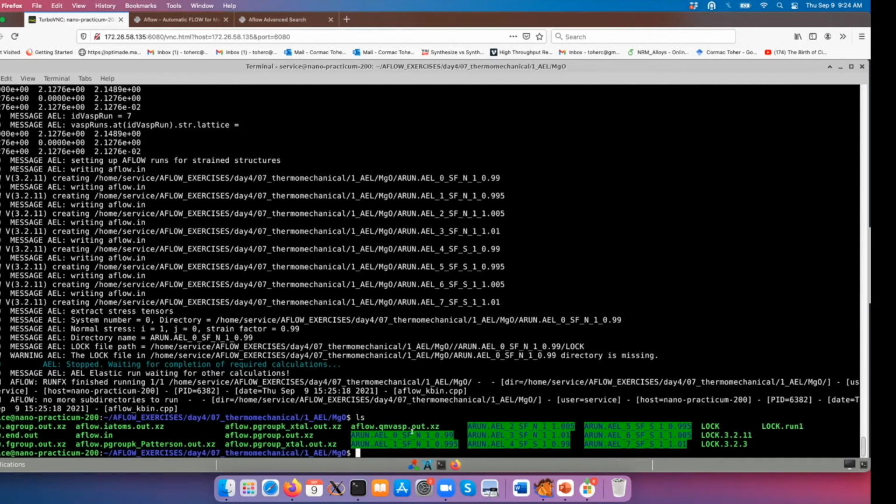So in this case, this is a normal strain that's in the first independent direction. That's a 0.99, so that means it's a 1% compression. All of these strains here are normal strains. Here you can see that's a 1% extension, for example, for this one here.